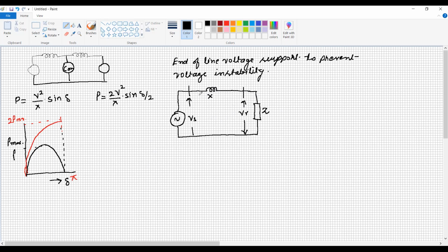If we consider this, there may be a deficit of reactive power or a surplus of reactive power, and because of this, the voltage VR will not remain constant for all load conditions. Under such conditions, the characteristic of load voltage, the load voltage profile, can be represented by the power, in PU, as voltage versus power.